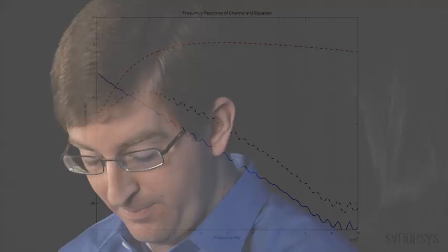Can we do something about it? Can we minimize the fuzz or even get rid of it? That's a really good question, and that's fundamentally what we try to do with equalizers. An equalizer is a circuit which attempts to flatten out the frequency response of the channel. So instead of having this frequency-dependent loss, we ideally want a flat channel response.